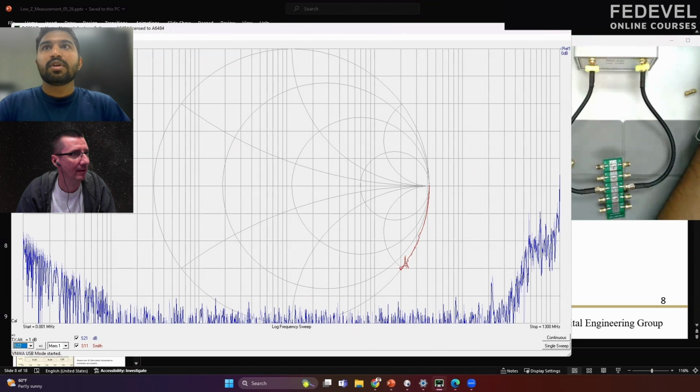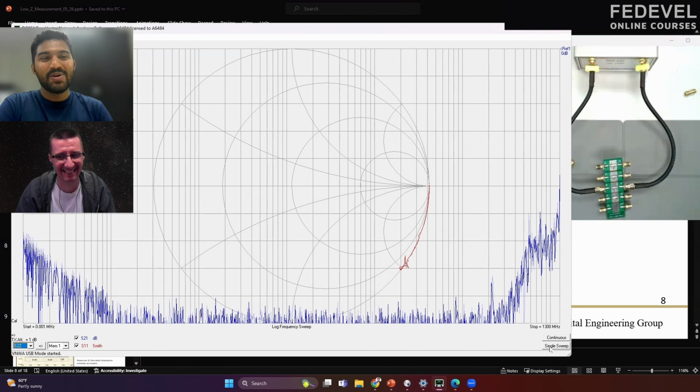application and we can either go to measure or we can directly take a sweep. So before we actually take the sweep, now is the question, Robert, what do you expect it to look like? A 0.1 ohm resistor, yes. I would expect for lower frequencies 0.1 ohm impedance, and then for higher frequencies there will be some kind of influence of the inductance of the lead or something like this. I don't know. Oh wow, perfect, perfect. You're good. So let's try and actually take the measurement.